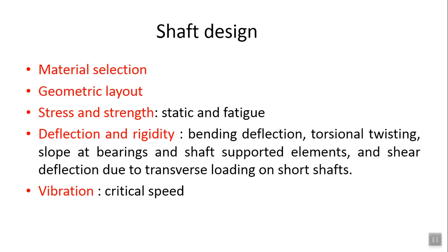Now when we try to design the shaft, obviously we have to focus on the material, then we have to decide its geometry, then we should understand the stresses and strengths. Again, it is a rotating part, so fatigue will come into the picture. Then we have to understand deflection and rigidity, where we will understand bending, torsional twisting, and others. We'll try to understand the vibration also, where critical speed will come into the picture.